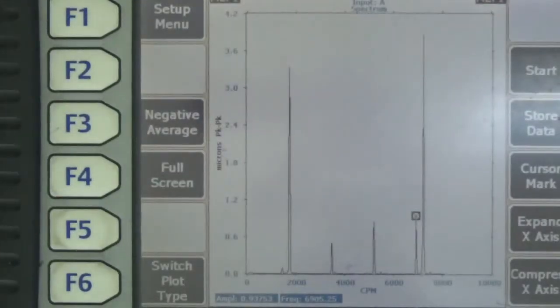Now you can see here that there are 4 blades in this fan, and the RPM is 1721. So what will be the frequency generated by these 4 blades? We will multiply RPM by the number of blades, and it is equal to 6884 cycles per minute.